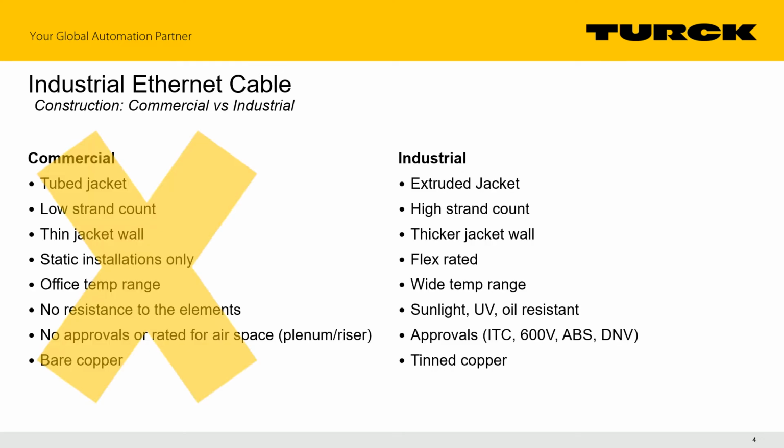To put it simply, industrial Ethernet is the opposite. It should have an extruded jacket which hugs the individual pairs, holding them together and maintaining the twists, while also providing extra thickness to prevent against tears and abrasion. If you were to hold the cable in your hand, the outer jacket would be smooth, not convoluted, and you would not feel the individual pairs move within the jacket.